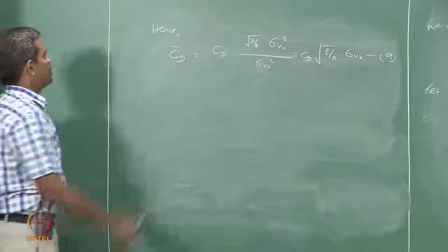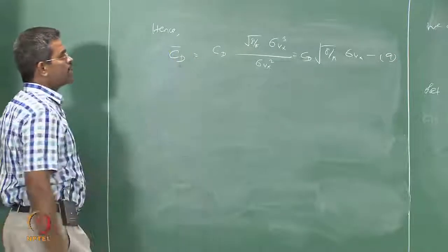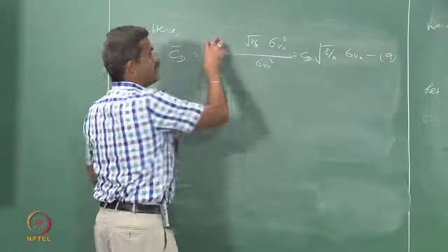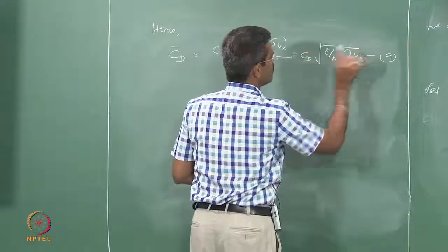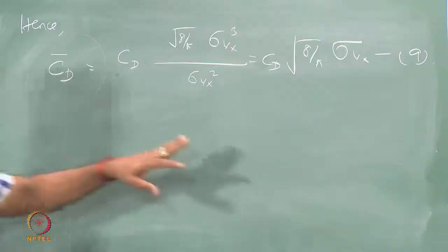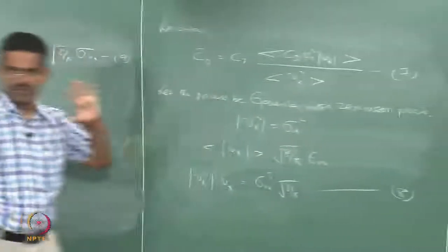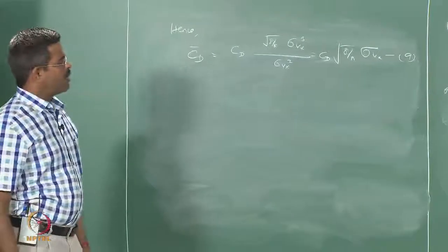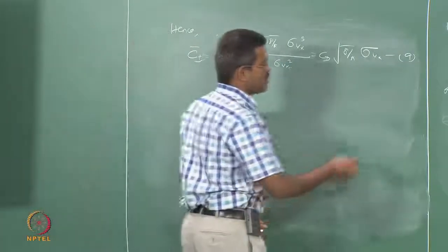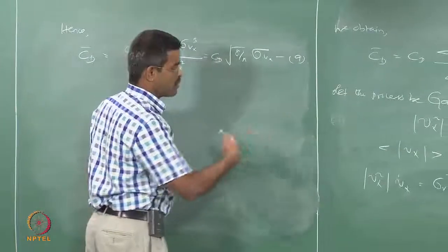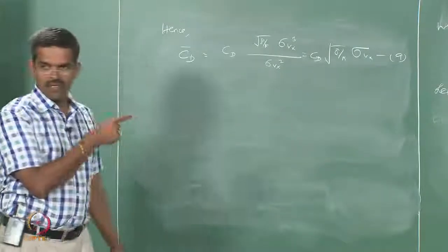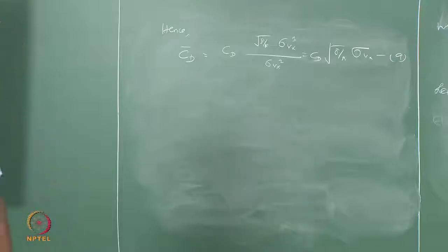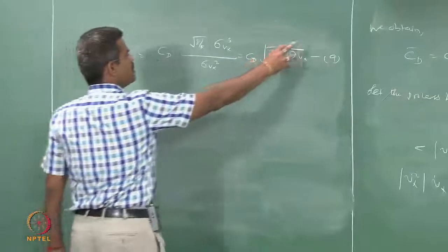So, if you presume that a linearization of drag term exists, it will be a multiplier or some weighted factor of CD, which is given by this number, whereas this is not Vx, this is sigma, which is known to me for a given process being Gaussian and zero mean. We know this for the velocity. And I think we all know how to compute this. If you got velocity variation or water particle velocity variation horizontal for a given wave field for a specific time domain, you can take a mean average of this, find the standard deviation and variance of this easily for a given statistical process. So, it is easily obtainable for a given Gaussian process.